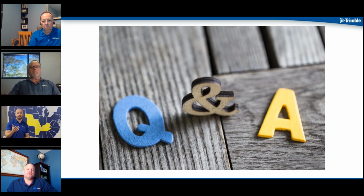So Sean, did we do okay with that one, or do you have something to add? No, all great answers. The only thing I would caution customers is, once they get to a certain height in the building, I would highly caution against using reflective targets.